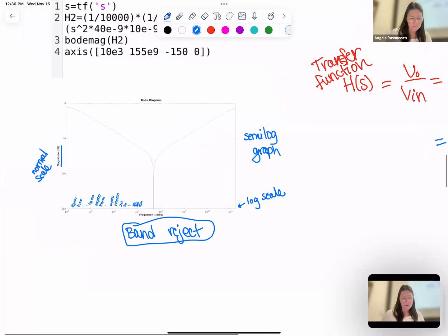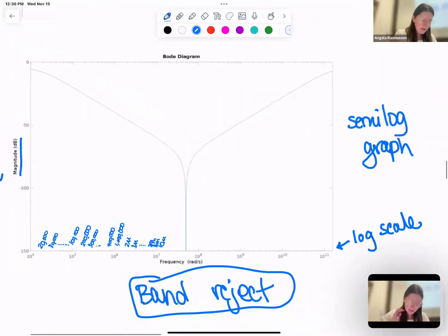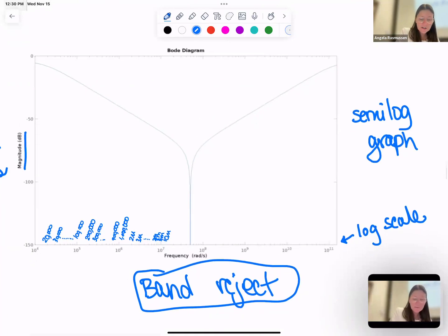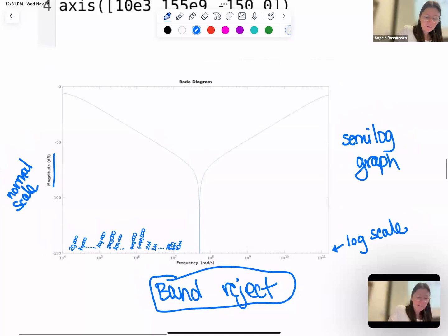Okay, so we're going to make an estimate here of omega C1, at 70%, I'm going to say is somewhere around 10K. This doesn't show it very well. Again, in MATLAB, it's a nice thing: you can take the cursor and click on the graph and move it to find these corner frequencies. So you can find where it's flat and then go down.